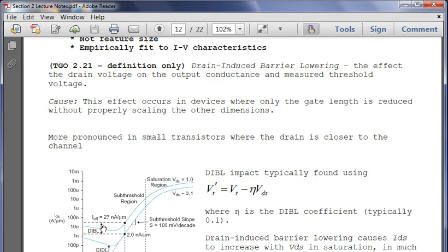You have to account for lower voltages in smaller feature sizes. So you have your normal threshold times your DIBL coefficient times the expected drain source difference, and that becomes your effective threshold voltage.